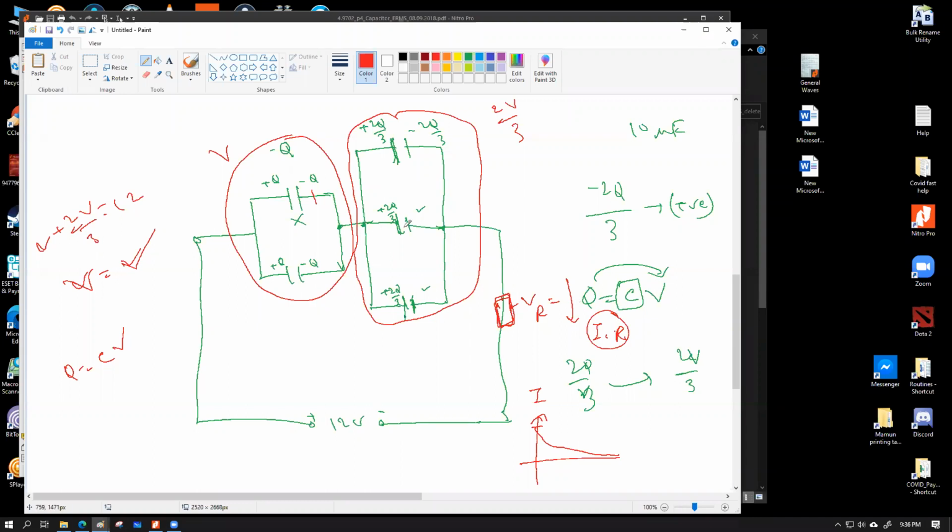So essentially all the voltage will be consumed by these two. So that's why I said that when the charging process is finished, all the voltage, which will be equal to 12 volts, will be consumed by the capacitors only. The resistor would become unworthy of any voltage, because there is no potential drop there anymore. Because current is practically zero.